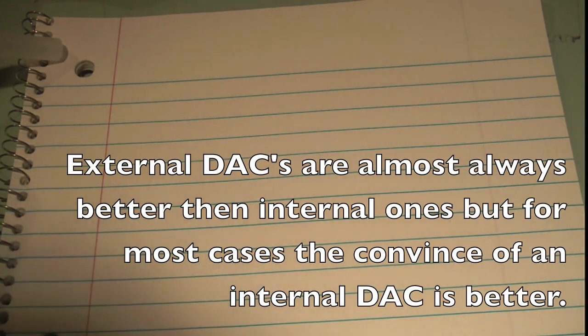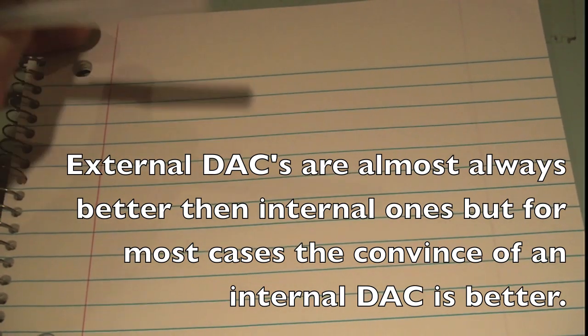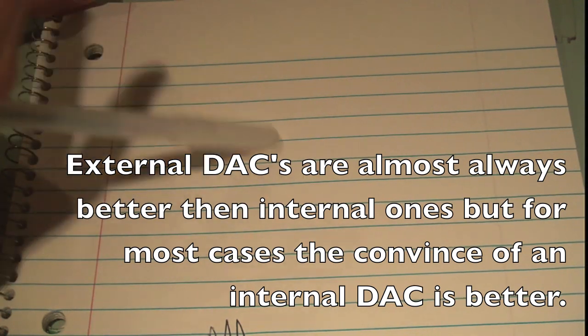Although, if you have the money, an external DAC is probably the best option, unless your microcontroller has an internal DAC. So that leaves us with an R2R ladder and PWM with a low-pass filter. Both of these options are pretty close in terms of cost, but in terms of simplicity, an R2R ladder is a bit more complex, and it requires a lot more resistors.